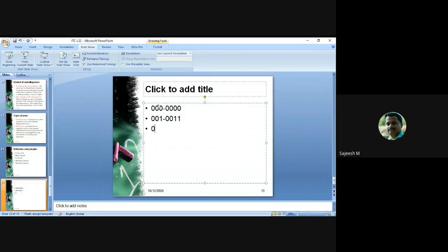If it is 010, then the code word we can write as 0101. We are using an even parity check code. That is parity check coding. Then next one is 011 as the message bits. Then we add 0 as the check bit. That fourth bit is the check bit. We can say here the parity bit appears at the rightmost symbol of the code word.